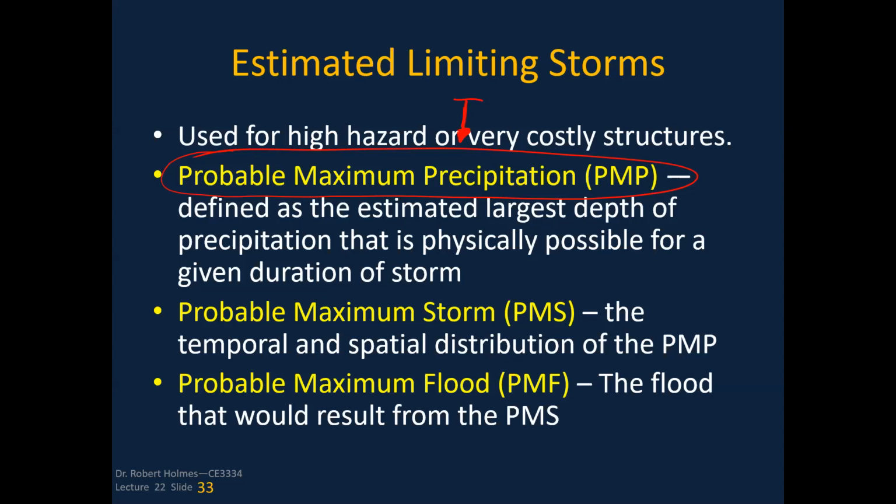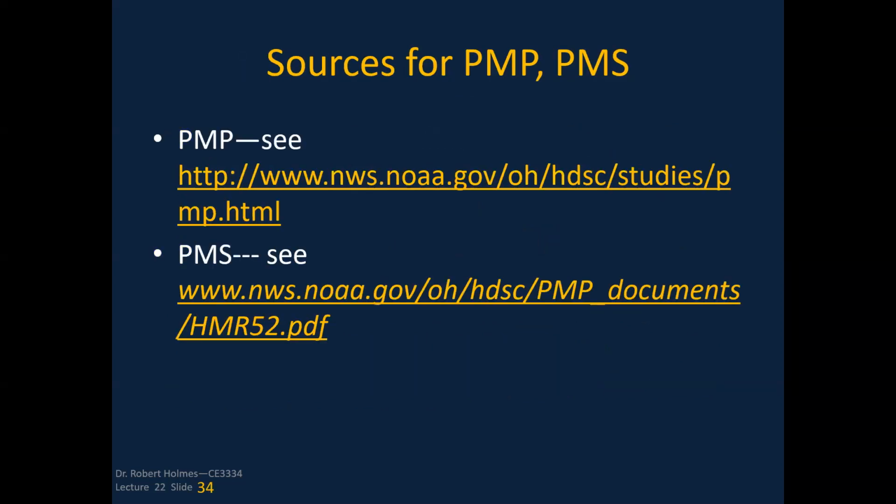And so the Weather Service, it was the Weather Bureau at the time, looked at atmospheric conditions in certain parts of the country. If we looked at the juiciest atmosphere that we could imagine and we extracted every bit of the moisture out of the atmosphere, which never usually will happen, but it could, what would that look like? And so you come up with the probable maximum precipitation. You can see the various publications; there are various publications for around the country.